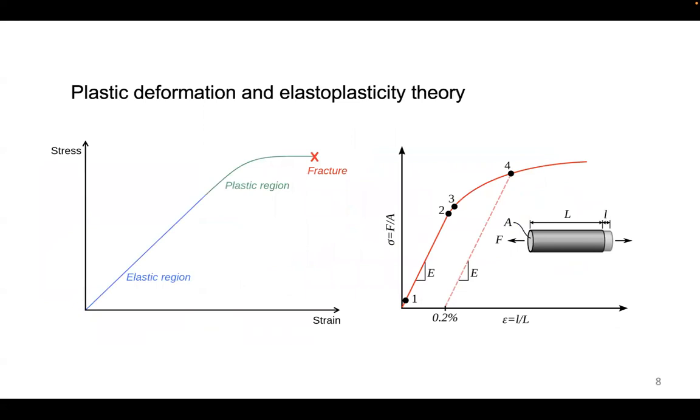Okay, so here I'm going to use the elastoplasticity theory, which is actually different than the last time where we used the recurrent neural network. I'm going to explicitly define the regions that are called elastic, regions that have no memory. I'm going to say that at some point the material yields, okay? And when the material yields, it enters the regions where it has memory. And then at some point you're going to break, and we won't cover the breaking part in this lecture.